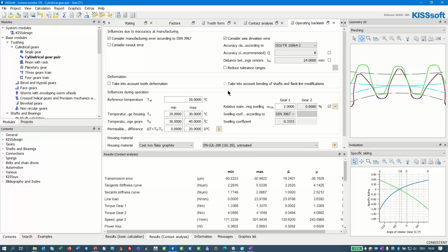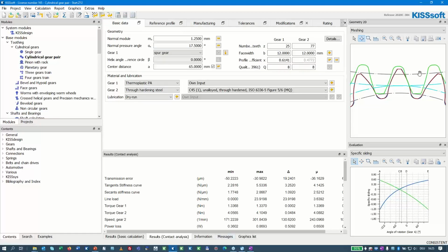If the shrinkage does not have an exact pattern as we have in the tooth form calculation, how can we control the micro modifications? And a question related to that is, what DIN class of gears are physically achievable for plastic gears? Maybe we can combine these two questions.